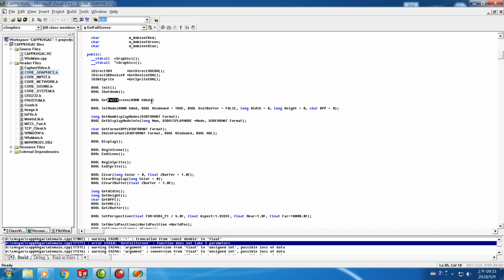In here, the original parameter is only window 1. There isn't a second parameter. So we say one parameter is correct. We have to remove the one after the window. That one is the reason for the error.